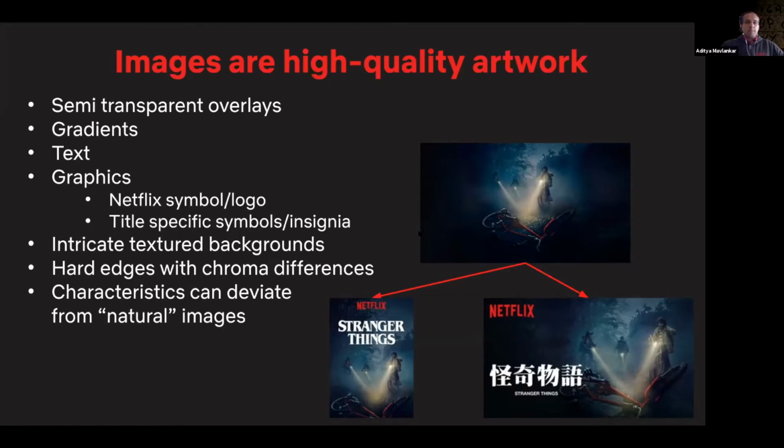And when such hard edges are present, the color subsampling is very important. For example, if YUV420 is used, we can see color bleeding and all sorts of color artifacting. And some codecs unfortunately don't have 444.